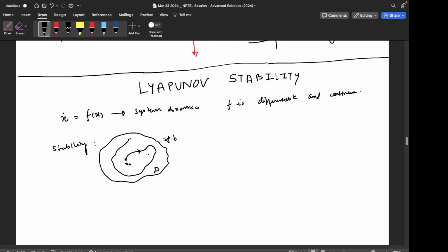Sir, here you are representing the system as a point, sir. No, no, not as a point. So x0 is the initial state of the system. That's a state space diagram. Basically, let's say for the spring mass block, the x position and velocity together form the state, right? So the plot will be like the initial conditions. The initial condition will be, let's say, zero position and some non-zero velocity, right? And I will let the trajectory, and this will be the trajectory of the system.